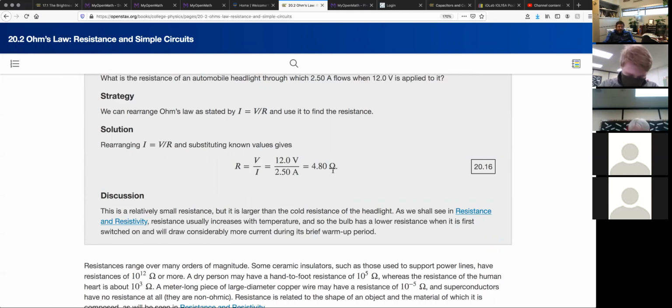So light bulbs can handle that kind of current less and less as they get older and older, because incandescent light bulbs get so hot that they literally are boiling the metal off of the filament. So the metal actually gets thinner and thinner the longer you burn an old incandescent style light bulb. And then eventually it's so thin that when you try to put that current through it, it just heats it up and pops it really quickly.